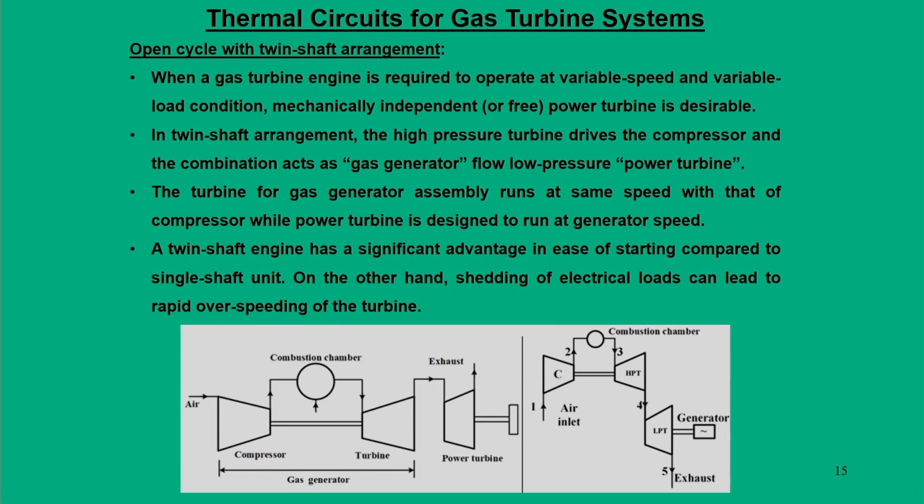So, in that case what we can do is divide it into two shafts. One shaft, that means compressor and turbine, are joined together and synchronized. The other is the power turbine, which we normally call a free turbine. This power turbine is a free turbine, it can produce power freely. It has nothing to do with the integrated shaft requirement for the compressor and turbine assembly.